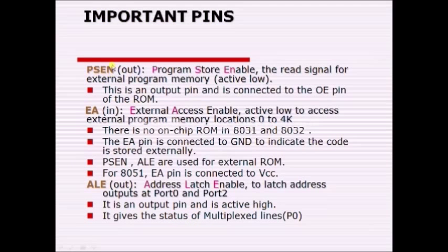Now let us see one more pin, that is PSEN, which is called as program store enable, and this is an output signal from the controller, and it is an active low pin, which is nothing but a logic 0 is supplied to activate something. This pin should be connected to OE pin of the ROM. As we know that whenever a logic 0 is received by this OE pin, then the processor can read the data from the peripheral. So that is why this PSEN is connected to OE pin of the ROM.